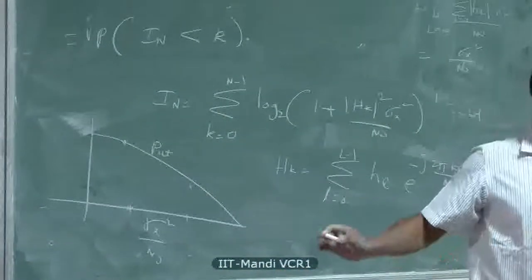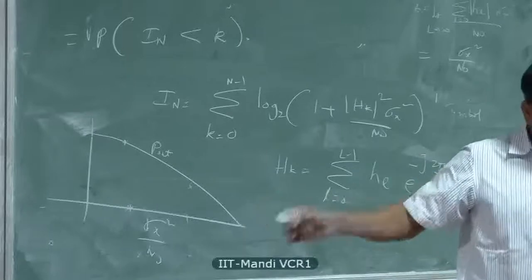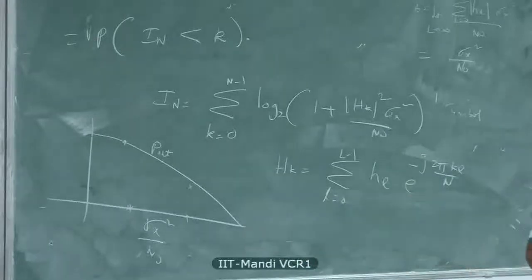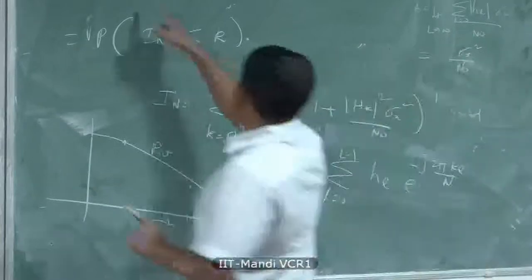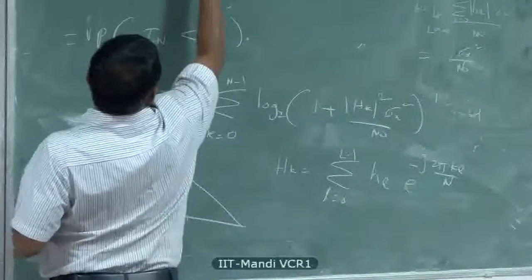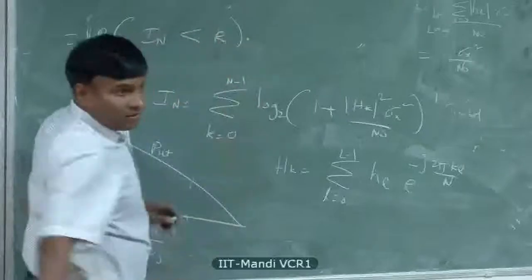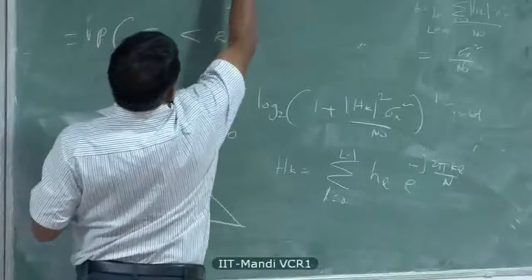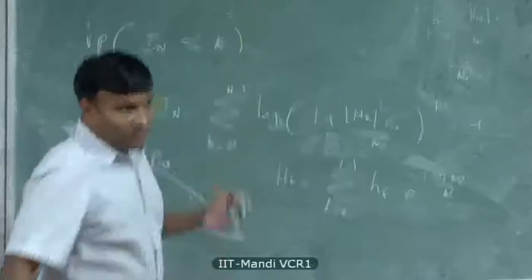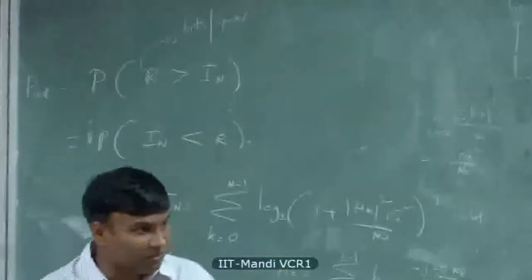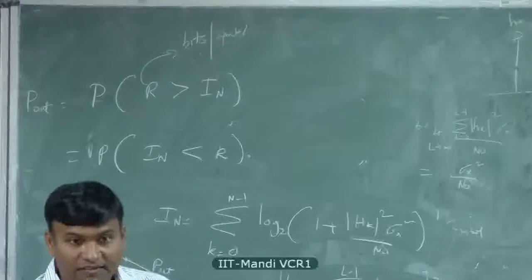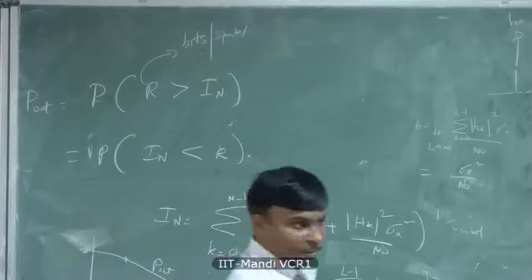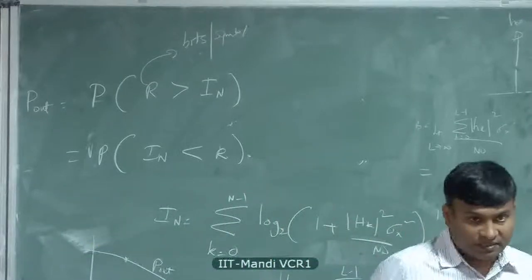It doesn't even depend on the length of the frame, particular modulation, particular coding. It doesn't depend on anything else. It depends on the rate R. What is the units for R? Bits per symbol, let's say, channel use. And R is typically chosen in the order of 0.5, 1, 2, 3. 1 is like sending 1 bit, 2 is sending 2 bits per channel use.